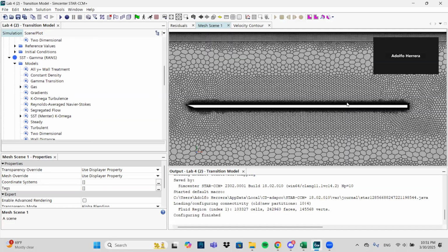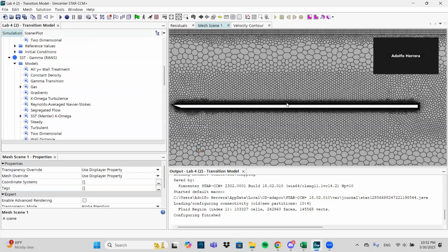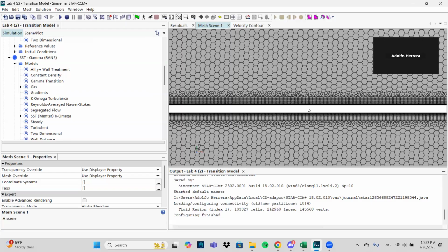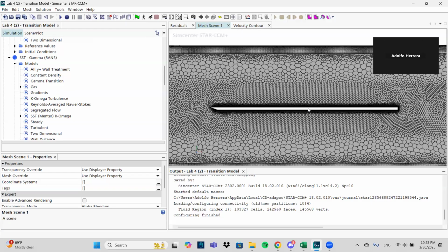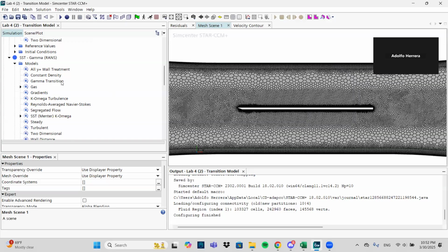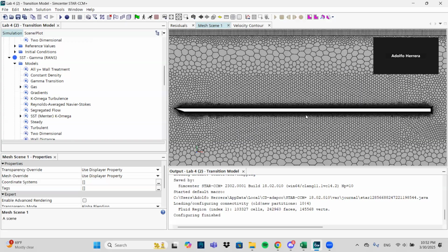Just in case, because the Reynolds number for the entire plate does not exceed the laminar flow regime, so we're evidently not going to get any turbulent boundary layer in this sim. But as a precautionary measure, the simulation was run using this physics model, where the solutions did not vary as much from the laminar model sim.